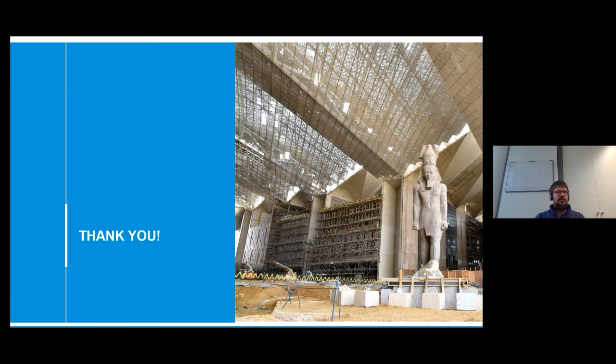That's going to be difficult to explain like this without being there in real. But when you do the chloride analysis, you have to do it by slices of concrete to see if the chlorides are coming from the outside. You really see if the chlorides are inside the element or coming from the outside. This is in short. I don't know if you understand the idea. Yeah? Well, that's something like this. Thank you.